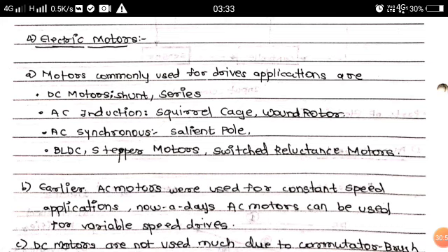Some motors can be electronically controlled easily. For some machines it is very difficult. For some machines, if we use some rheostats or something like that for controlling the power, then it is easy but it is very costly, or it is uneconomical. The power loss is very high. So we have to consider so many parameters. Accordingly, we have to select the type of the motor.